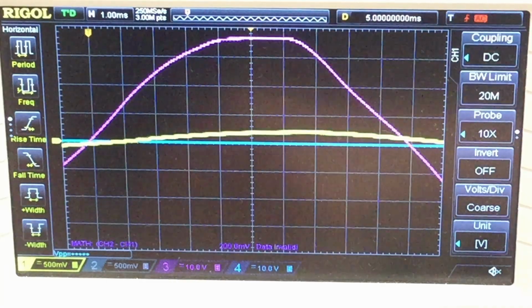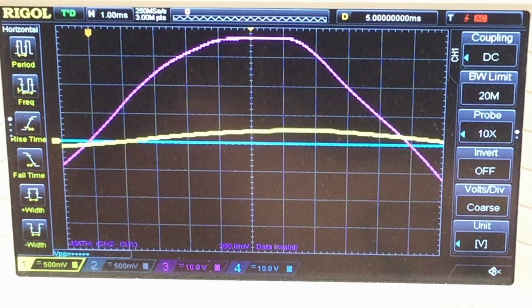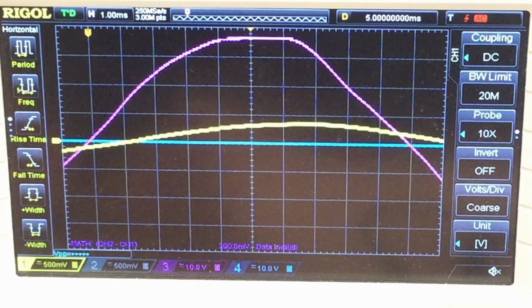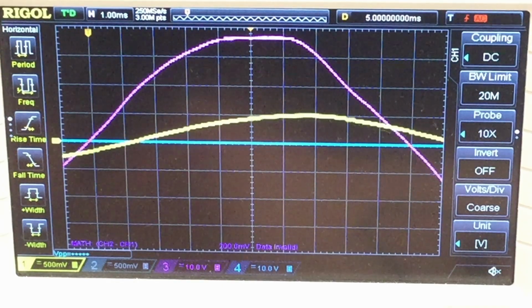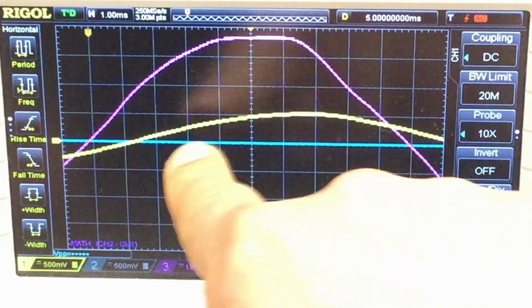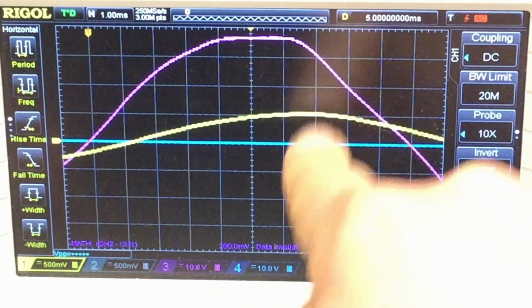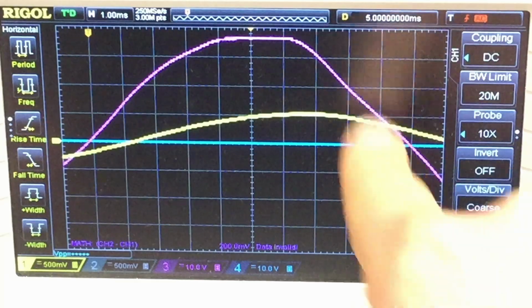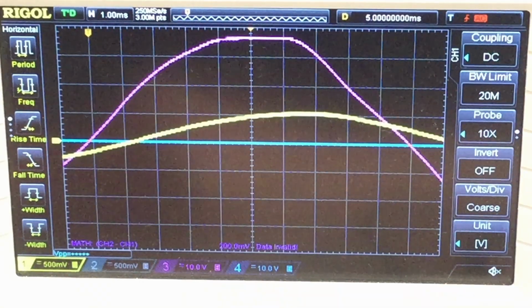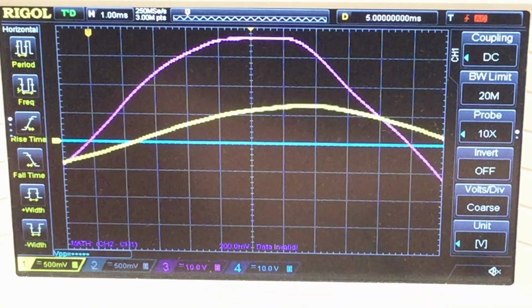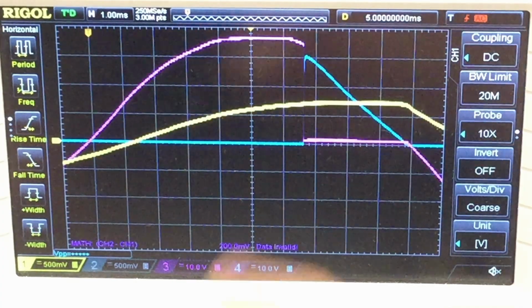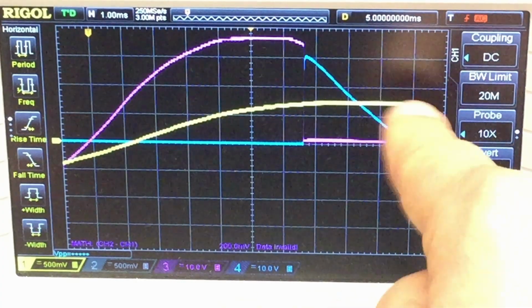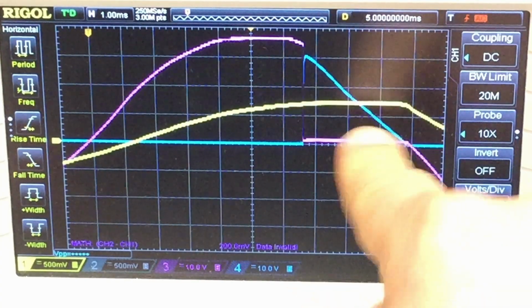And with the capacitor in, I'm now able to switch it on later, because you see the peak gate voltage is phase shifted to my load voltage across the main terminals. Yeah, and now I'm really here, well, not really at 0 degrees, but you get the principle.